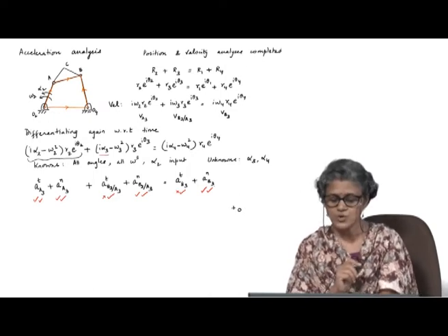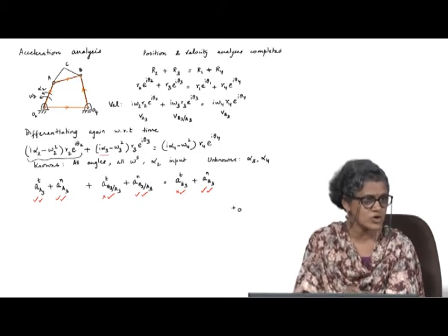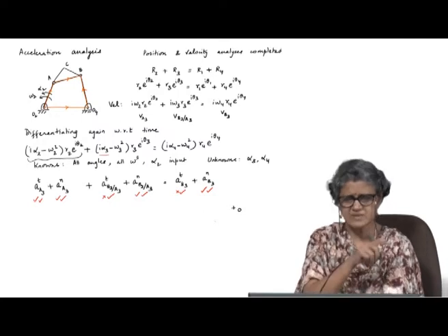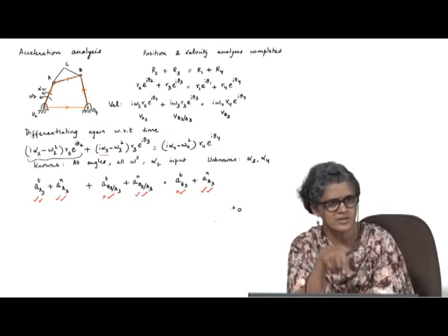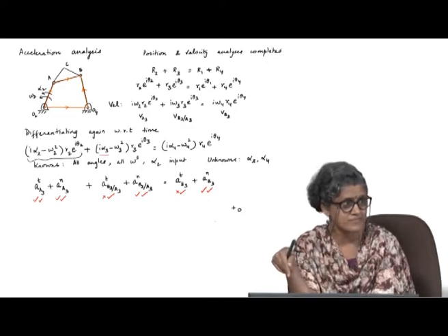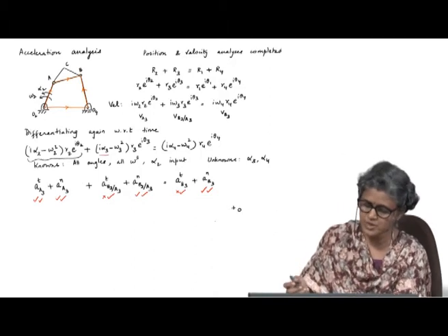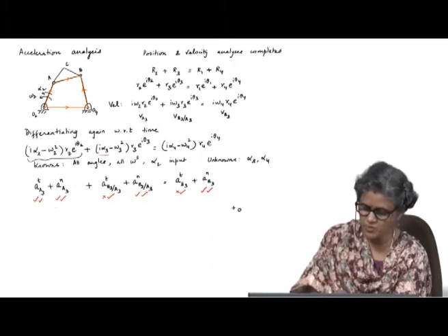Okay. So, you see here again I have two unknowns. So, I should be able to solve this vector equation. Only thing is, in the velocity equation we had only 3 vectors to create the polygon. Here we now have 6 to create the polygon, the acceleration polygon. Okay. So, let us start with what we know and what is absolute.